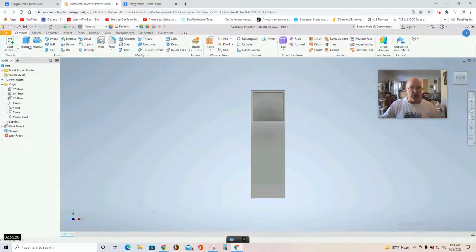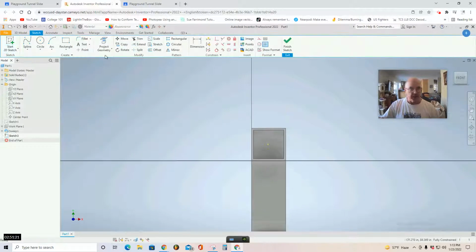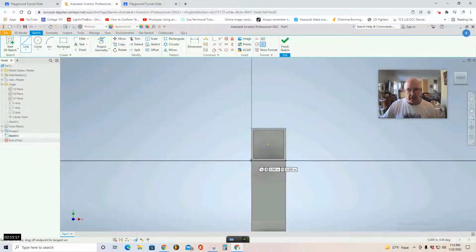So you'll start a 2D sketch, select this profile, the double square profile, click, and then return to the line tool. And from the left side here, dragging left along that x-axis, pull a line out and then type 18, enter, and then straight up, 90 degrees, another line, 30, enter. Hit escape 3 times. Now I want you to use the line tool again.